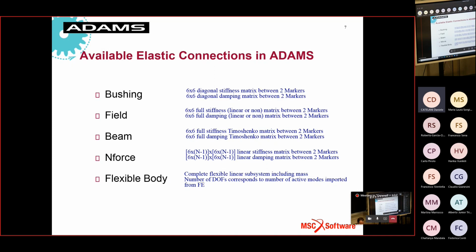But it is valid only in a linear range of deformation. So this technique is not valid when your flexible body has great deformation or displacement, or the behavior becomes nonlinear in terms of change of material characteristics, plastic phenomena, buckling phenomena, etc.